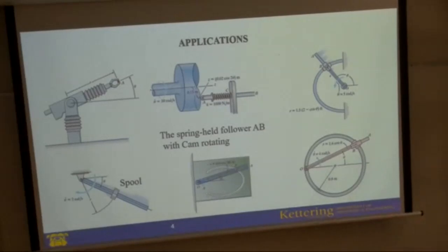Okay. Now, if you remember, and that was also a question on the quiz, to show the radial and transverse coordinate system, if this r shows the position, and I extend this direction outward, this is called the r axis. Perpendicular to this direction is called theta, or the transverse axis. It is positive in the counterclockwise direction.